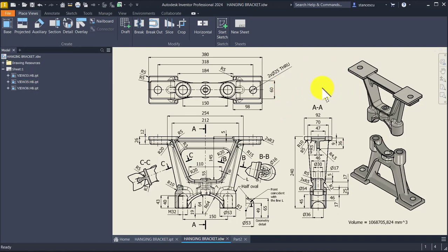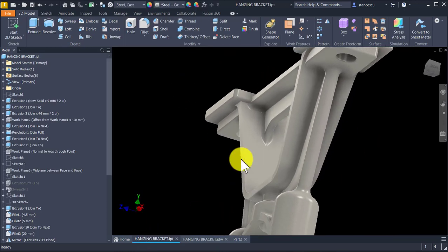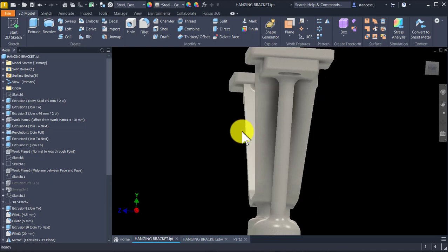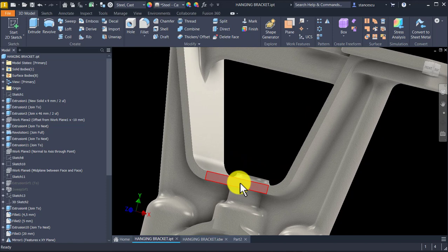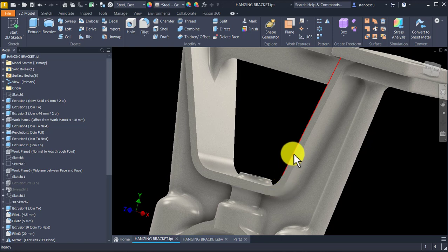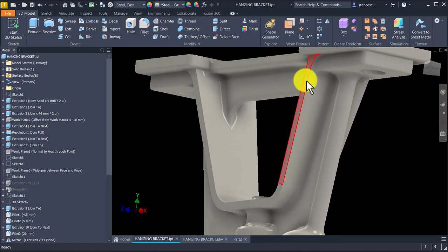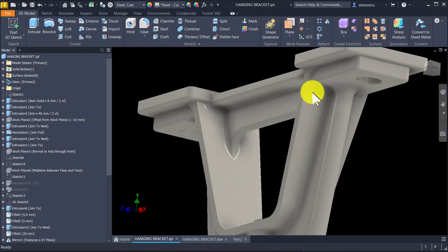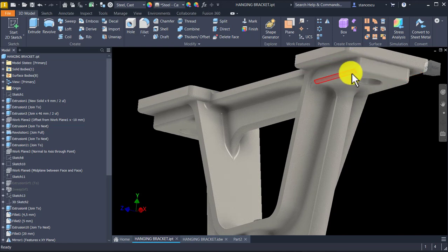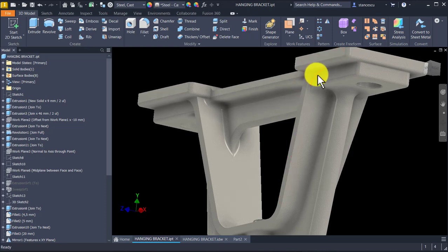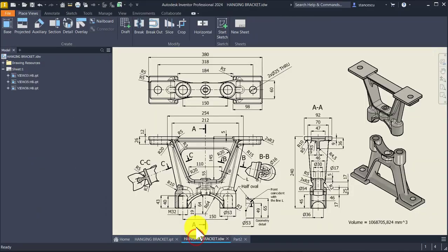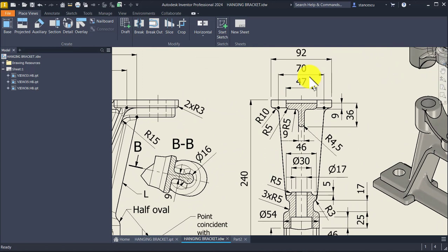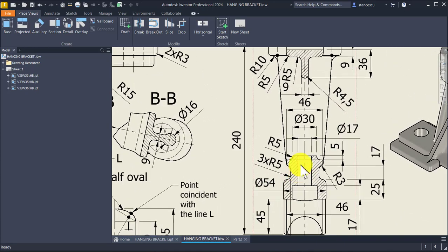Now we take a look at something very, very interesting. The most difficult part of this modeling. You see, this is not a parallel orientation of these two faces. So we have to create from this flat face to this different section up. Now we don't have this placed here and it starts on this face, it ends on this face. What are the dimensions? The dimensions are 70, or 70 divided by 2 for us, to this 46.